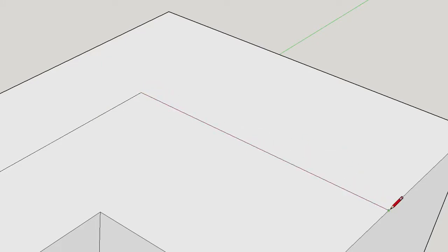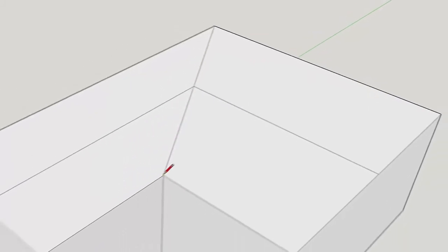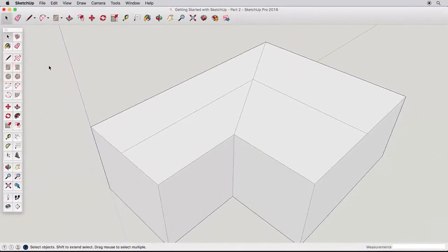Now that we have both ridges in place, simply draw the line where the roof will fold when we move the ridge lines. Use the Select arrow and click on one of the ridges. Then, hold the Shift key and watch the icon. There is now a plus-minus that indicates that you can add to, or subtract from, your current selection.